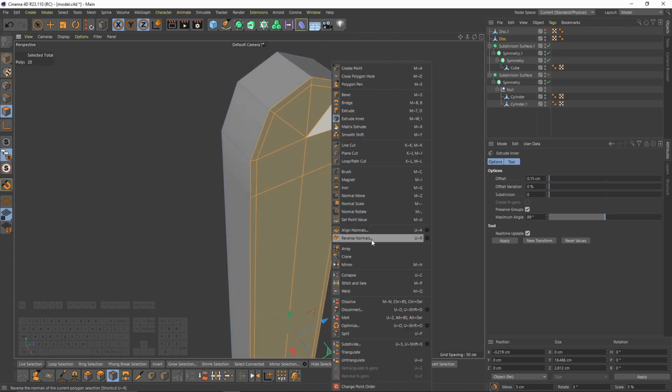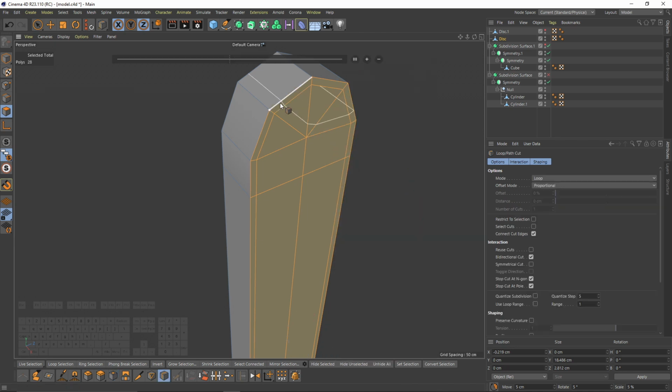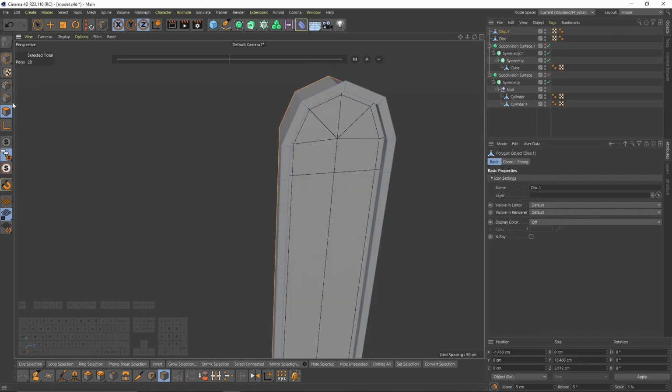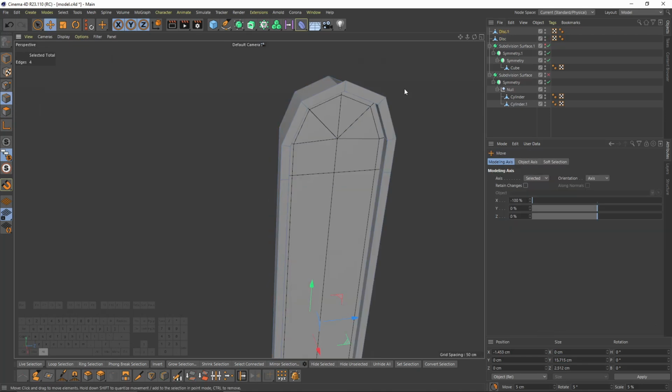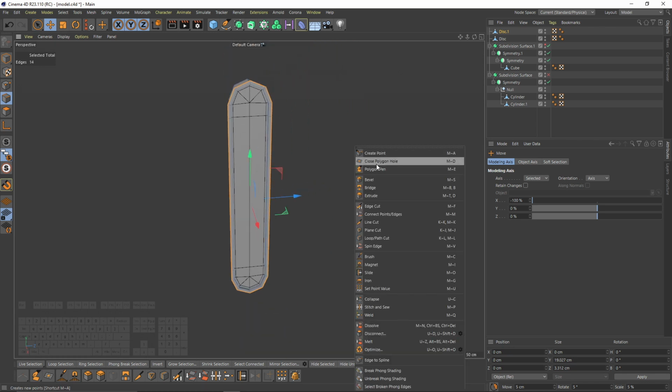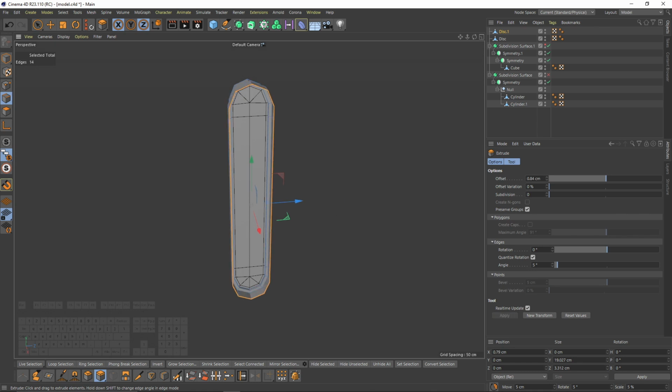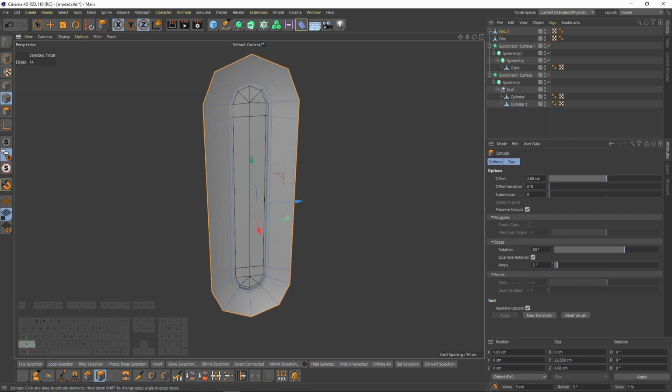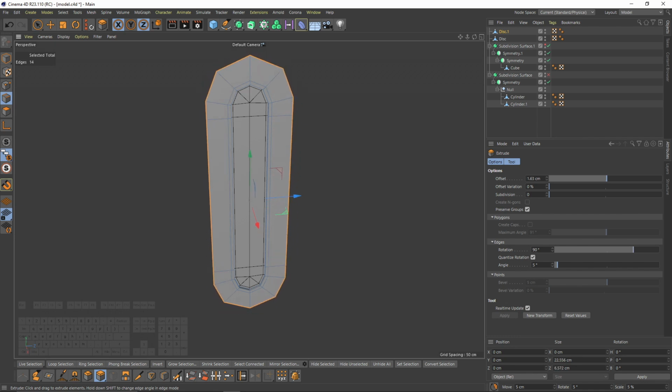And I think we will need another supporting path. So let's edit. Okay, now I will select the first disk object, double click on the outer edges, right click, extrude. So if your extrude is like that, press shift, then drag your mouse. This is gonna change the rotation of the extrude. Like 90 degrees is good.